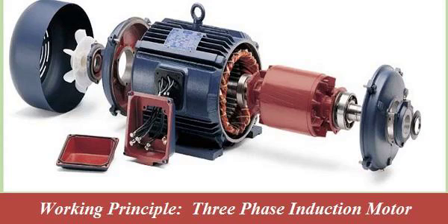Rotor. The rotor is the rotating part of the motor. It can be of two types, squirrel cage rotor and wound rotor. The most common type is the squirrel cage rotor, which consists of conductive bars placed in slots and short-circuited at both ends by end rings.